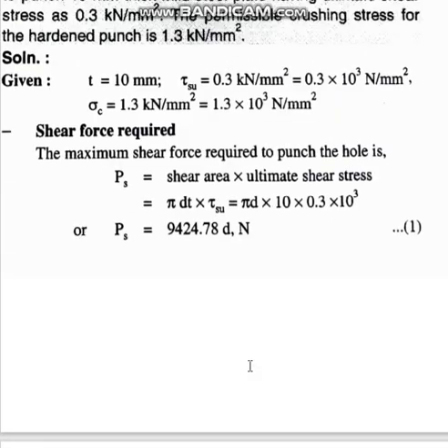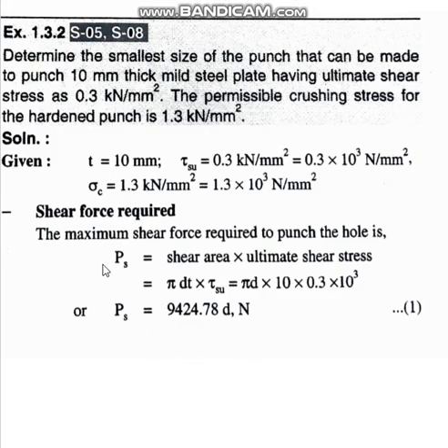Now first you find out what is the maximum shear force that is required to punch a hole. When will a hole be punched? If the force is more than the maximum shear force. So what is the shear force? You know that stress is load upon area. Otherwise, load is equal to area into stress. Shear area into the ultimate shear stress, that will be the shear load.